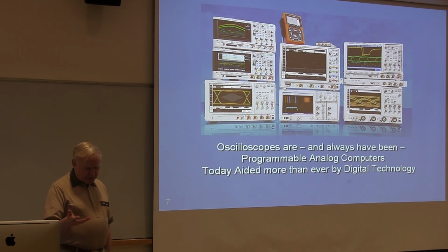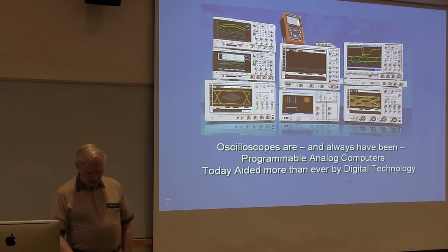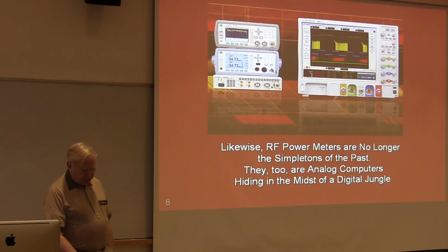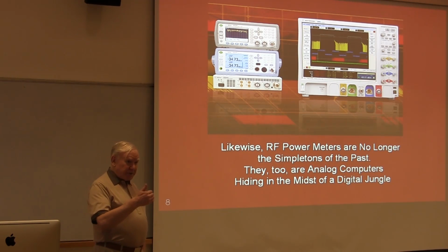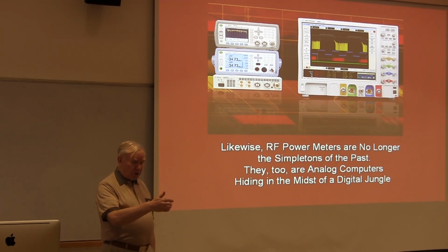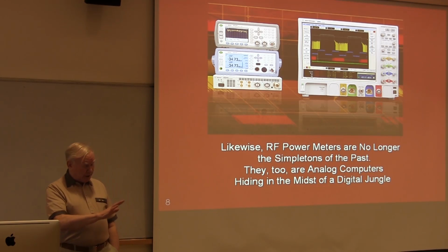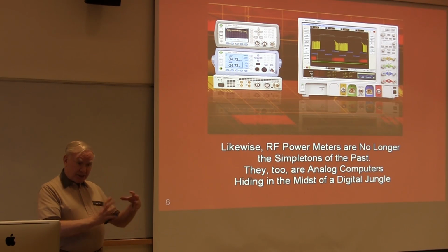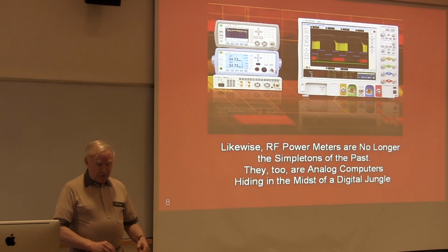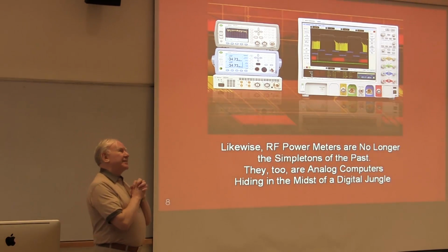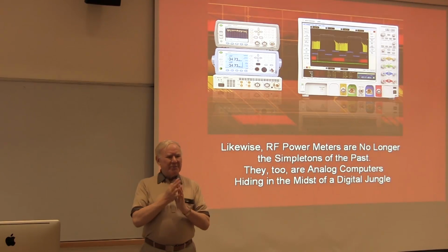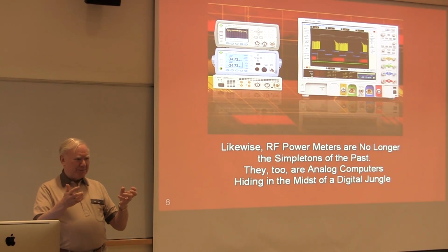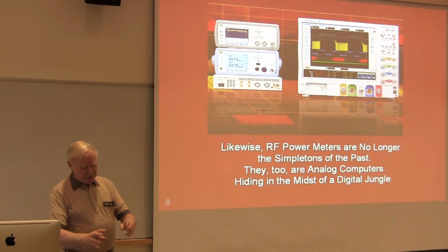Here we have scopes, which are a kind of programmable analog computer, if I can extend the definition. But they're getting more and more digital as time goes by. However, the interface between the signal we're trying to examine, which often, by the way, is a very fragile signal that we can't touch very hard, and the digital display, that's still all analog. It has to be. I don't think you can make an amplifier with digital components, except to say, well, an inverter is an amplifier. Yes, this is a special amplifier.